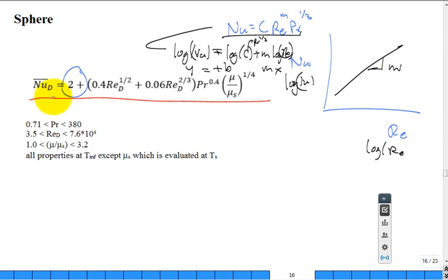But then you have this correlation, and it comes in with a constant plus a function of the Reynolds number to some power. I know it looks a little complicated, but that's going to look like it'll be out here and it'll go flat. That's what it looks like. The other one, as you continue to go to smaller and smaller Reynolds number, will continue to give a smaller and smaller Nusselt number. The other here for a sphere is that once you get down, it's just going to return a constant value of the Nusselt number for that correlation.